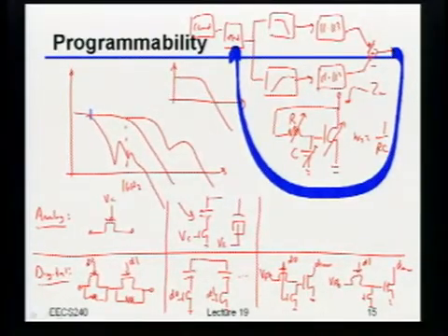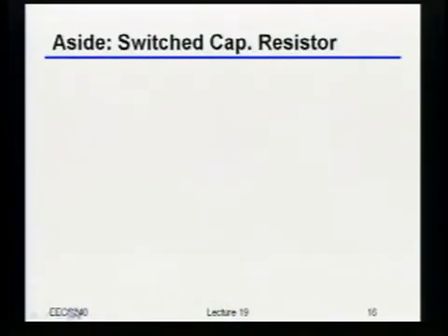As we talked about a lot way back in the beginning of the class, building big resistors is kind of painful because they're just big, physically. And they also tend to have a lot of variation. Well, it turns out there's a trick we can play to make resistors much more precise, and in fact perhaps even build very large resistors with a very small amount of area. The way we can do that is to use a capacitor as a resistor.